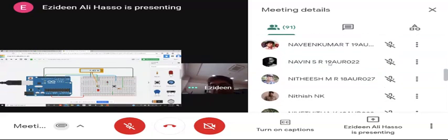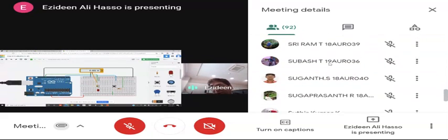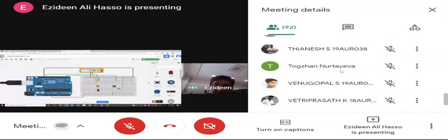It's supposed to read 5, but the simulator is simulating the real circuit, so because of the drop, the 5 volt doesn't stay 5 volt. There is a loading on the power supply, so it drops down by a few millivolts. If I just do a quick single click, look, the LED flashes, and the meter can pick this up.